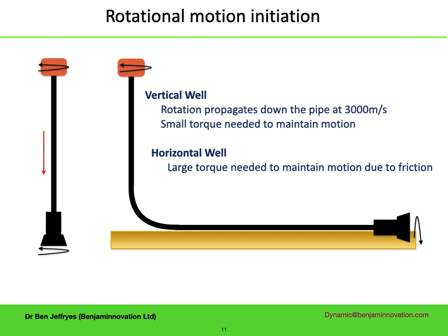It's different in a deviated well, especially so in a long horizontal. The drill string is lying on the bottom of the hole, and the weight, combined with friction, means a large torque is needed to maintain motion. But how long does it take between the top drive starting up and bit rotation commencing?